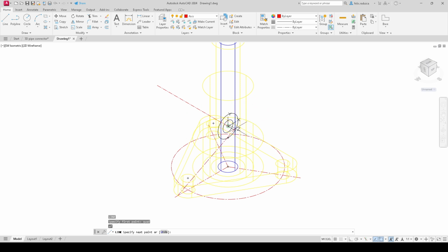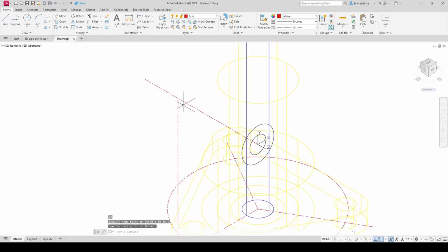Since we moved our coordinate system, Y is towards the top, so we can give the at symbol 0, 85, 0, and this is where the axis lines intersect, and this is where we'll have to bring our extrusion towards, so this point of intersection here.